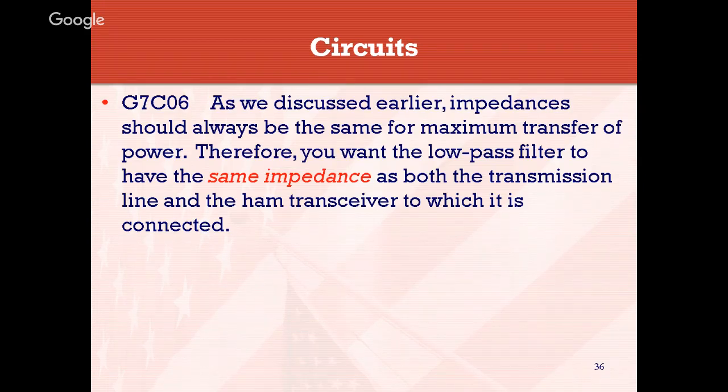When it's talking about a low pass filter here, it's talking about something to help minimize interference, say on your TV or radio receiver that might be sitting in the living room or the kitchen or maybe your neighbor's house. That low pass filter is only going to pass the frequencies necessary for you to operate your ham transceiver. And it's a rather broad low pass filter, so you don't have to worry about losing too much power with those, if that's a concern.